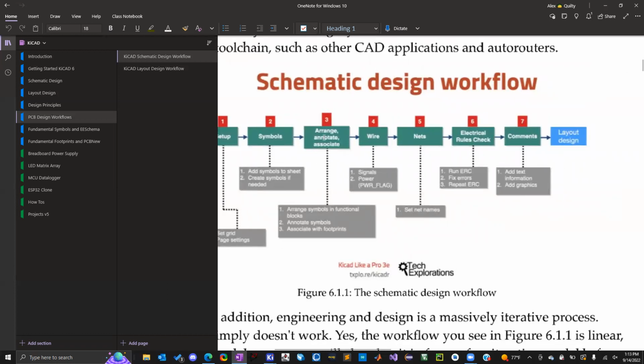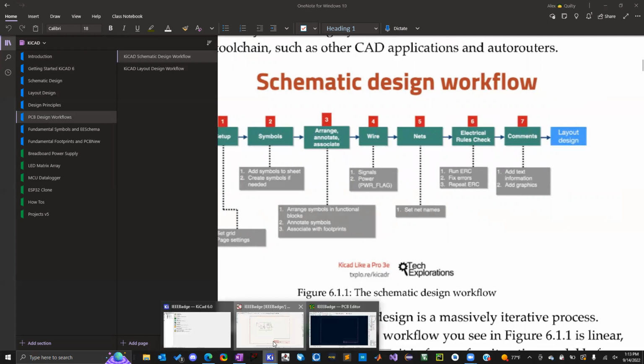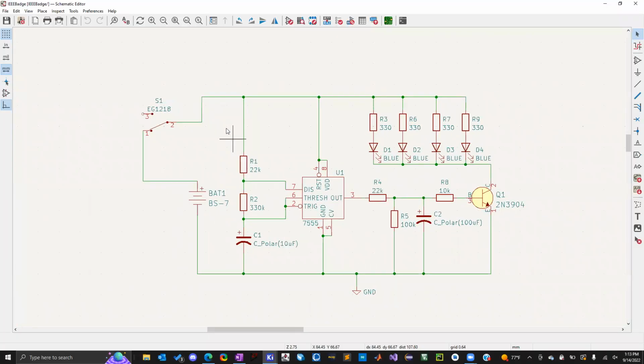It's called associating symbols. I can't remember if we went over that, but I already had it. But for any of you who didn't do it yet, these letters and numbers here represent, basically, KiCad's way of keeping track of what components are what and transferring it over to the layout, which will be the actual PCB.